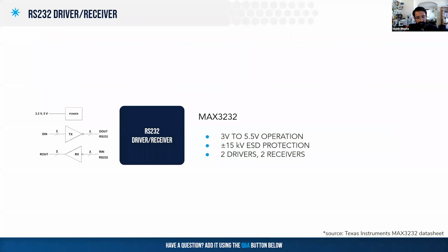It's a very well-defined protocol with plenty of parts available that do the translation for you. We are using a MAX3232 chip, particularly because it's compatible with 3.3 volt logic. Older RS-232 converters are TTL 5 volts. That won't work in our case, so we are using this one. It has built-in ESD protection, and it has 4 channels, which means I can do full hardware flow control: RX, TX, CTS, RTS.